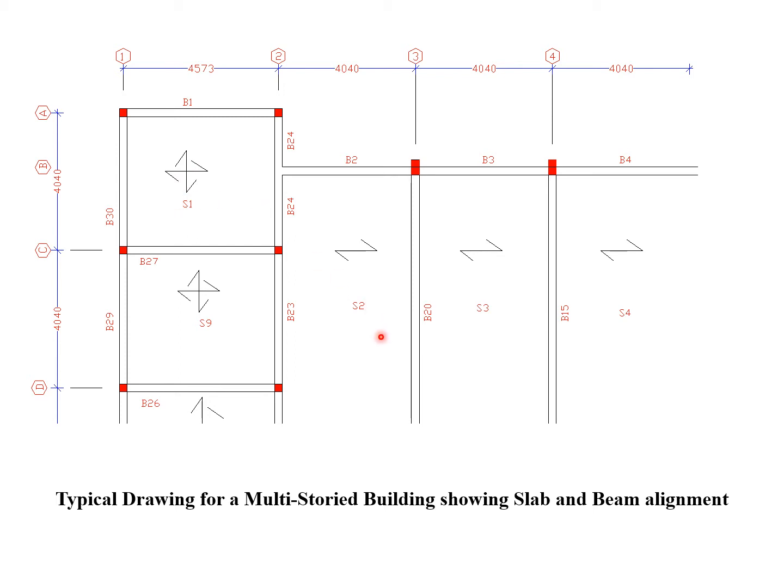Again, if you take this, I have 1, 2, 3. Again, this part I may be having one column. So the beam is being supported by a slab here. From the concept of arrangement, we know that it is a one-way slab since one span is more when compared to the other. So this part of this tutorial will deal with layout arrangements.